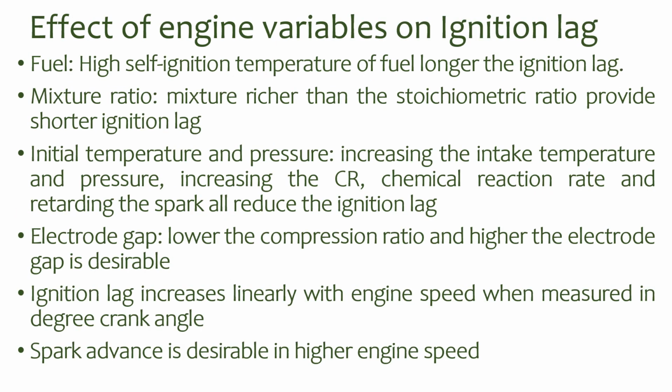Now we can see the effect of engine variables on ignition lag. When the self-ignition temperature of the fuel is high, the ignition lag will be longer. It will take time to self-ignite the fuel, so the ignition lag will be more.